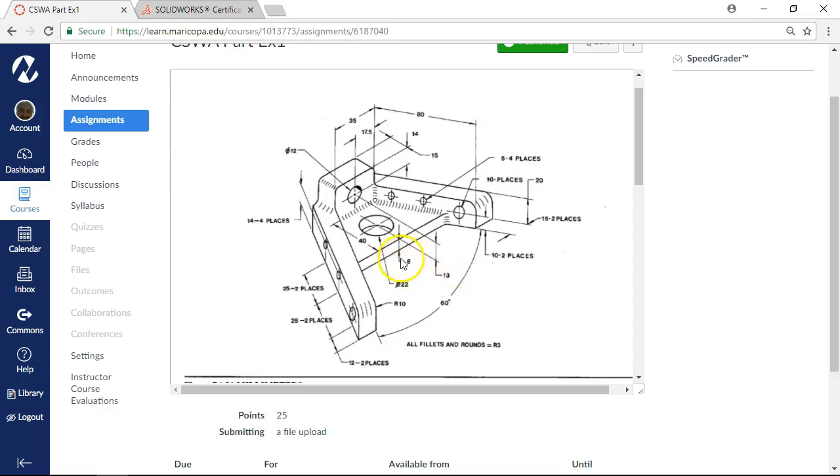So in this case, because the chain dimensions will usually throw me, those are something that I look for. So the 8, the 13, and this 14 are what's going to give me the overall height of the last block. All right, so just kind of going through that initial thought process, trust your instincts, look at the part and go, this is where the origin is at. So I need to start there.